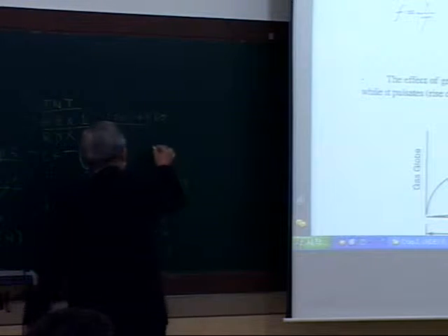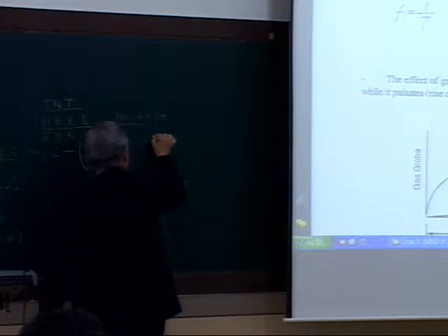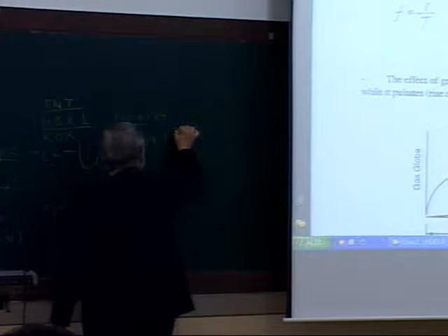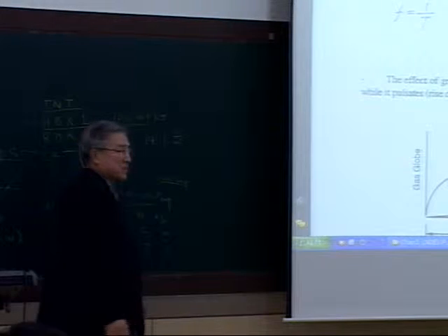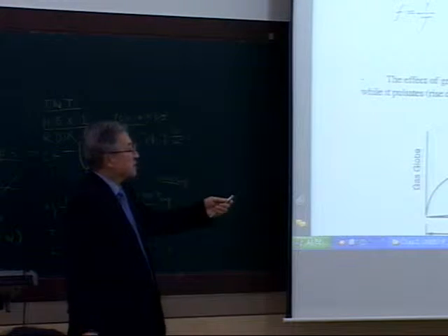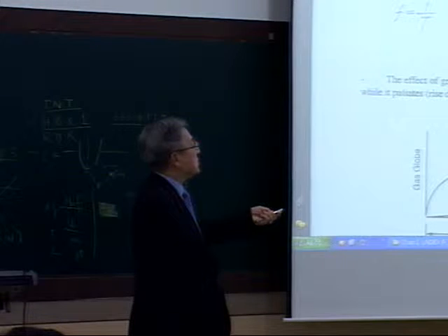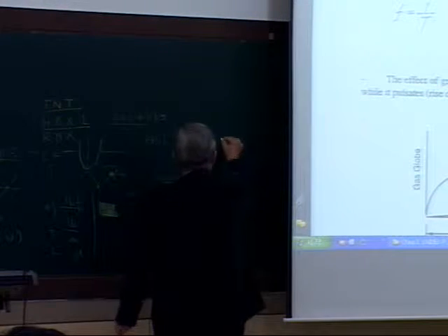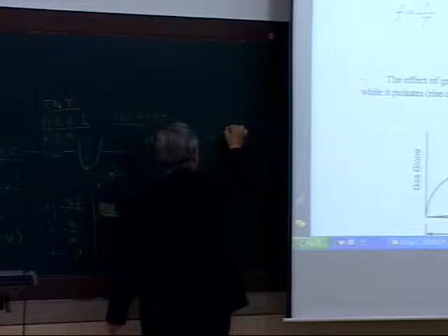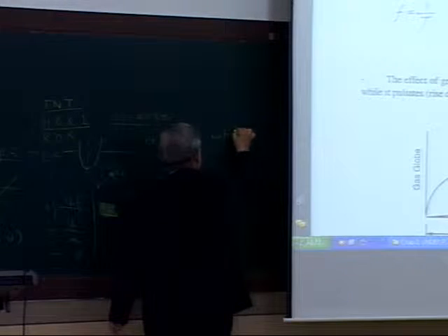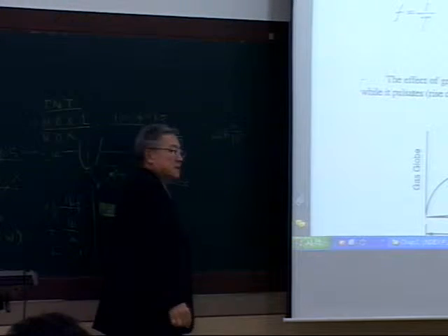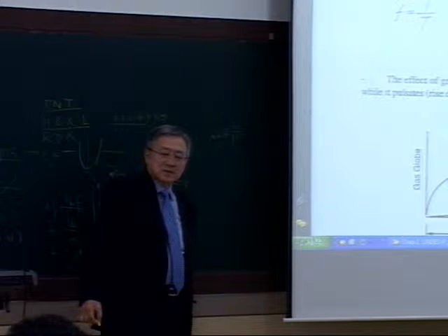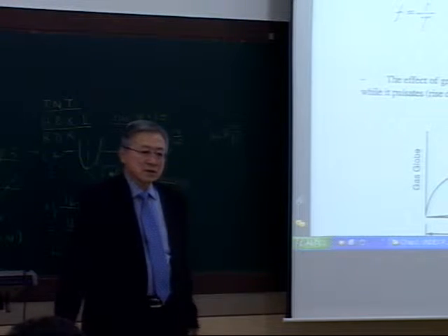Right. So 14.7, you have to convert. This is really pound per square inch. I want to convert this to pound per square feet, because later 62.4, that's 62.4 pound per cubic feet. That's the water weight. But you can use water weight in metric unit.